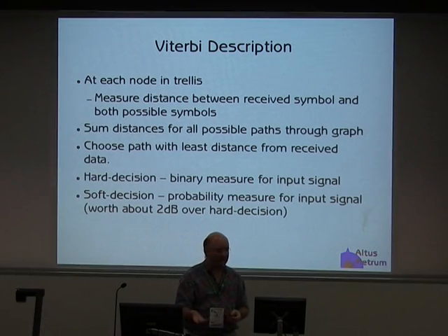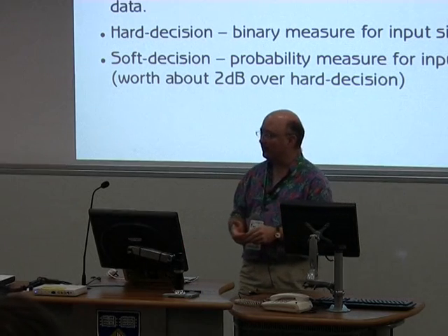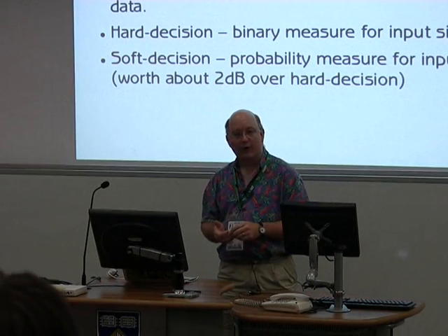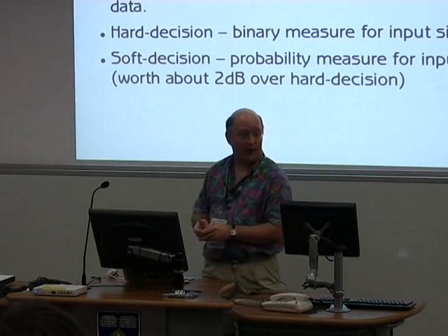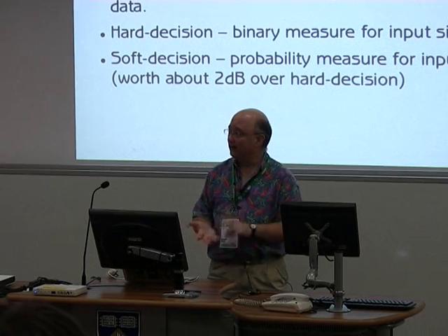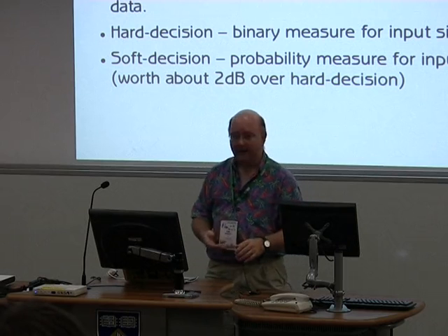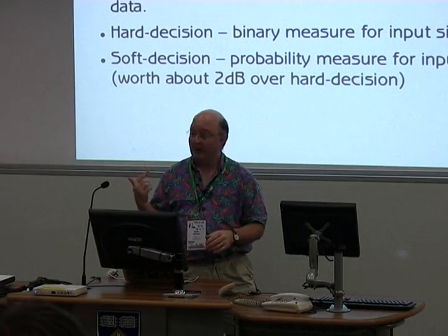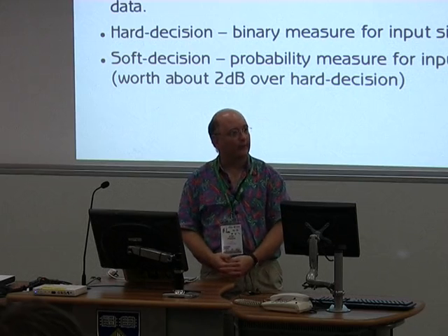The benefit of using soft decision is that you get about 2 dB in additional coding gain over hard decision. And again, guess what? That's free. You just have to have software that does it. There's no additional transmitters or receivers or antennas or power supplies. It's free receiving power.